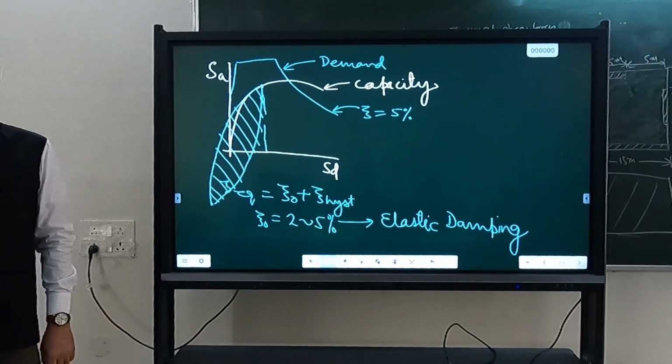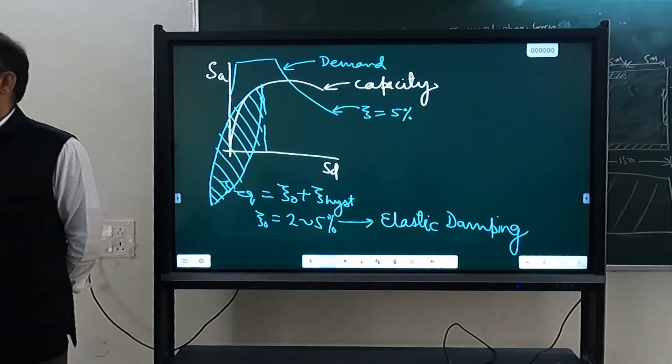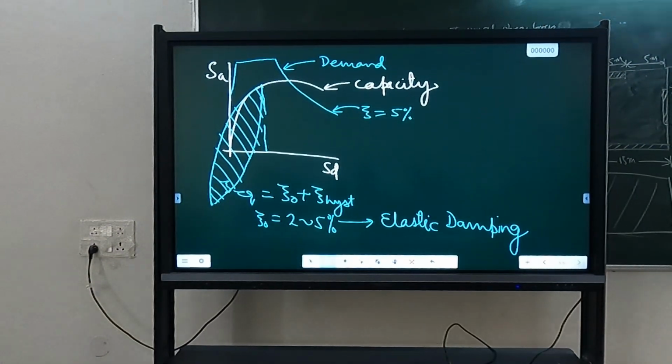that cycle. The cause of displacement in the plastic range is governed by the geometric nonlinearity. Geometric nonlinearity is also there. But more than that, it is the lateral force. If lateral force is not there, if earthquake force is not there, why will there be lateral displacement delta, and why will there be P delta?